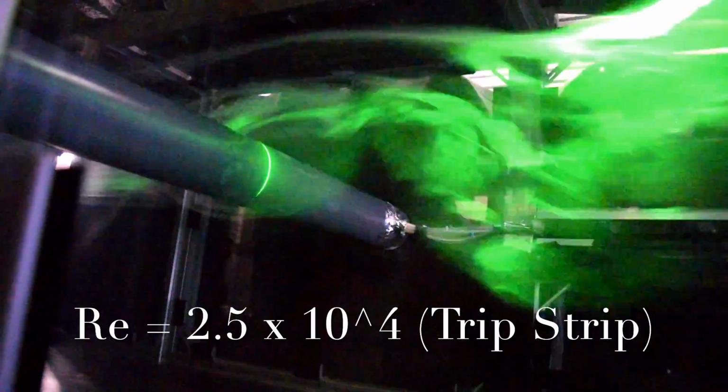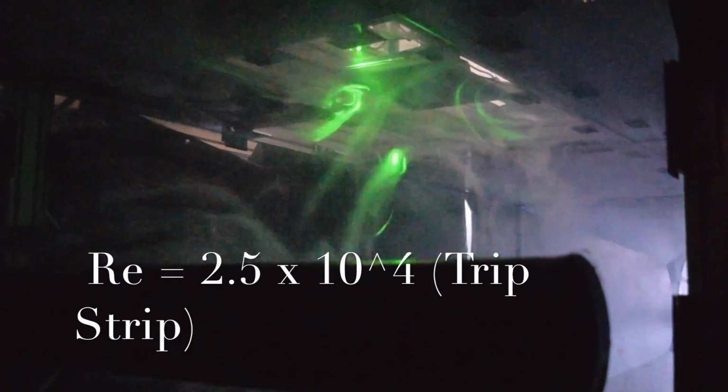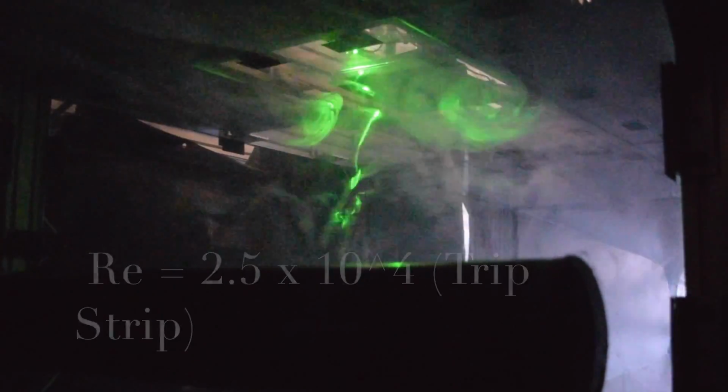In this video, you can observe a Von Karman vortex street, which is a repeating pattern of swirling vortices caused by the unsteady separation of flow of a fluid around blunt bodies. With the trip strip, the flow stayed attached to it for a longer time. On placing the laser perpendicular to the flow, we were able to observe eddies in the flow.